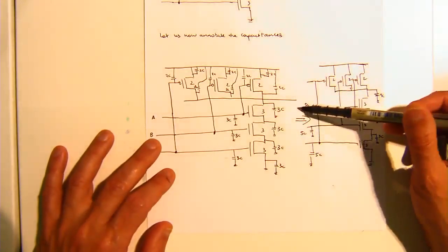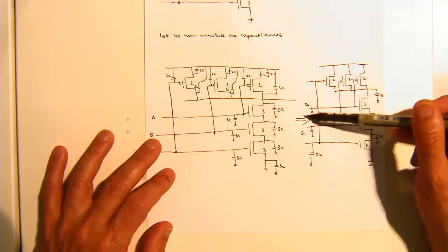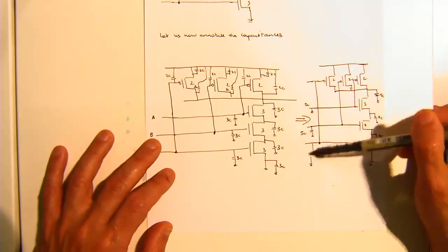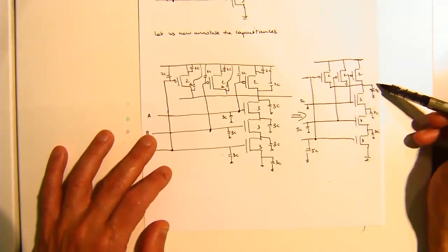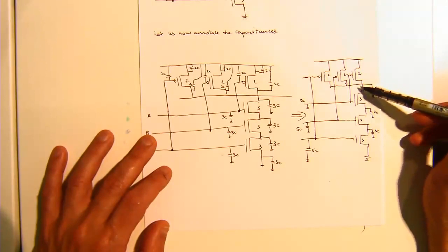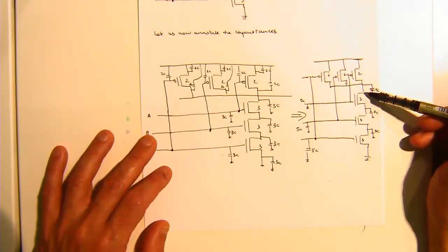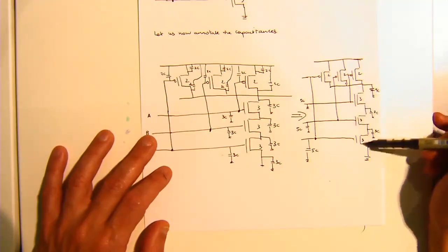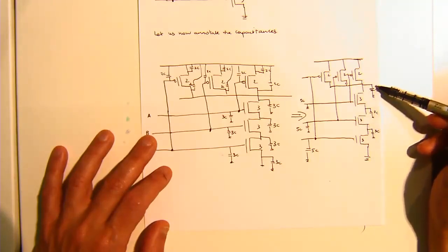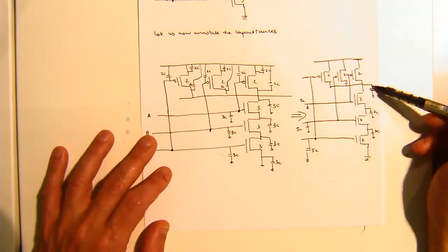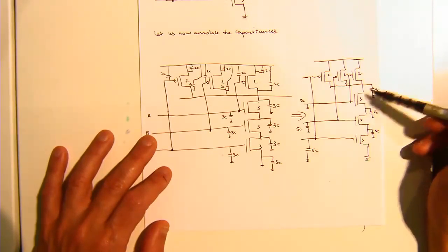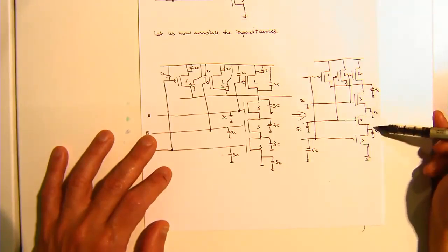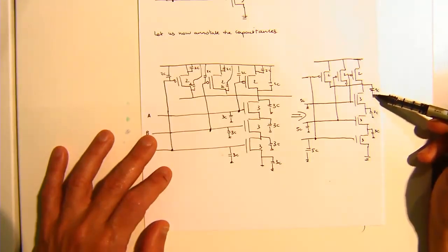At the input of the gate, each of these inputs has 5C of capacitance, and at the output we're driving 9C, depending on if the NMOSs are on or off. Because if they're on, we're not only driving 9C, we've also got to look at the resistance and the other capacitance that this output node might actually see.